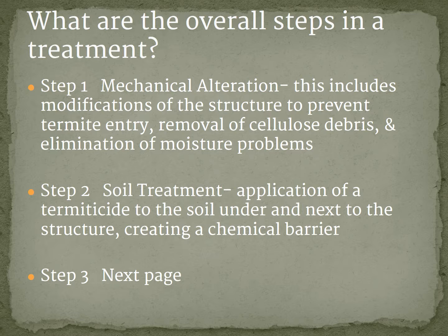I can't tell you how many times through the years I've gone to a house, found a moisture problem, and then dug a little deeper into the wood or maybe removed a little drywall, whatever the case may have been, and bam, the termites were right there in that area. So termites, especially the subterranean variety, love moist wood.